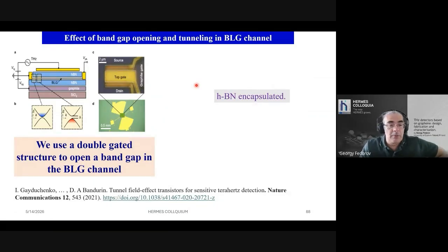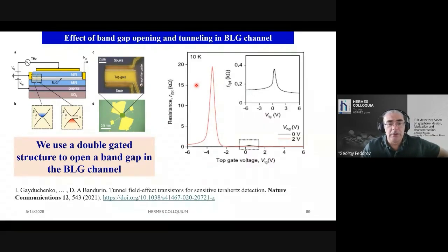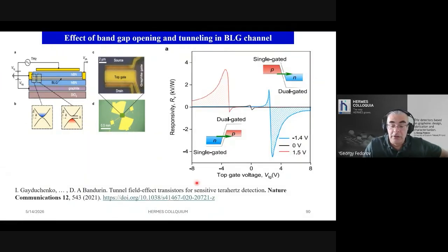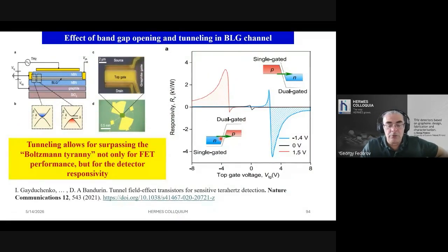Again, due to lack of time, I will try to skip some part of it. We were using double-layer graphene that has a band gap sensitive to electric field, so many things can be tuned if you have several gates here, and you tune some geometry of the objects to enhance tunneling through the Schottky barrier occurring at one of the electrodes. And I skipped the formulas for tunneling.